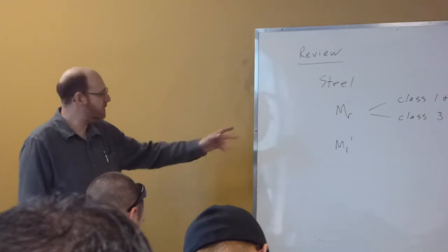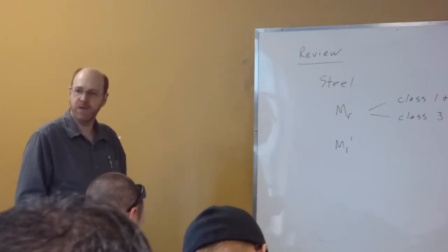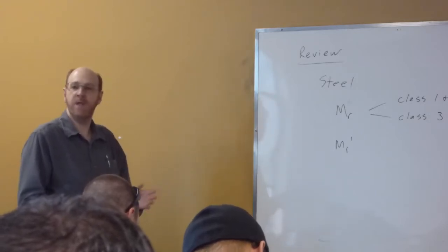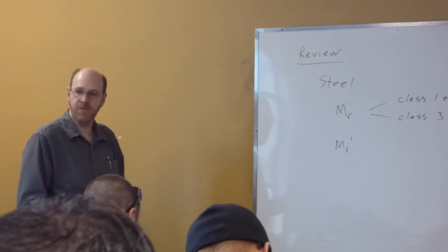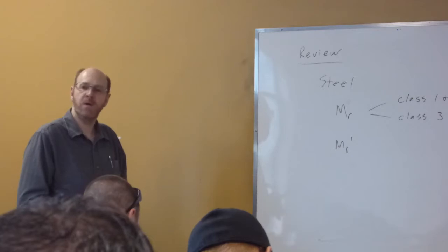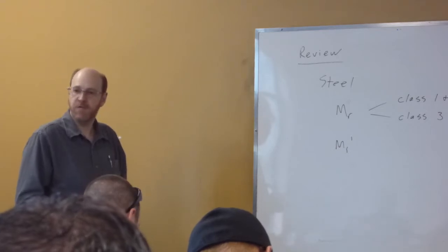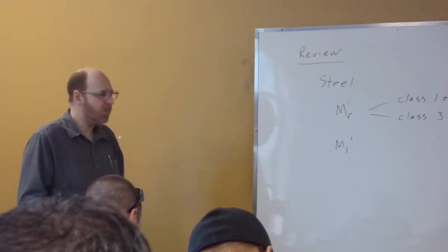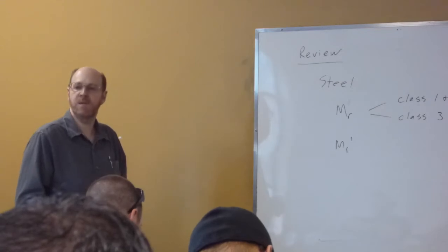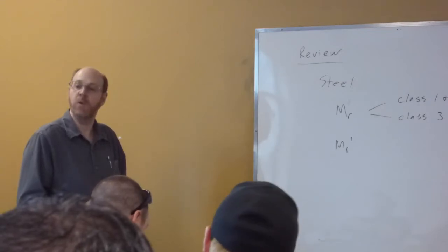Now we also looked at, for steel, several different methods for deflection. We looked at using our equations, like our 5W to the 4th over 384I equation. But we also looked at a BD-CD formula, where BD and CD are pulled off of a table and a graph. That one in particular is really useful if I'm dealing with statically indeterminate or with weird loading patterns.